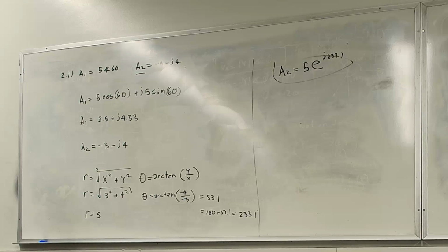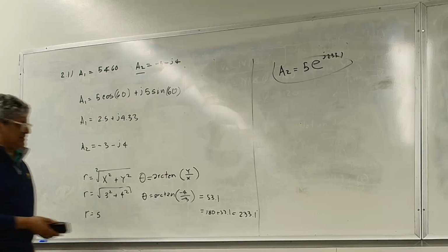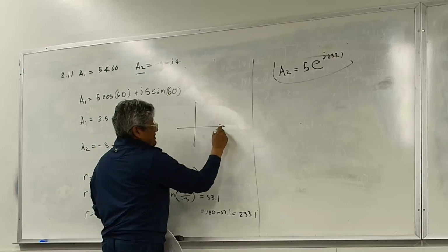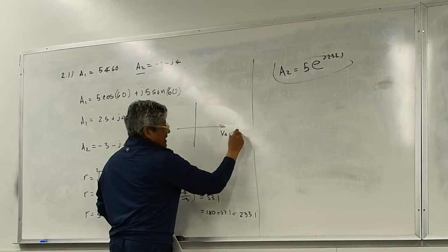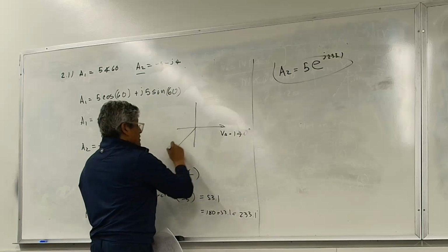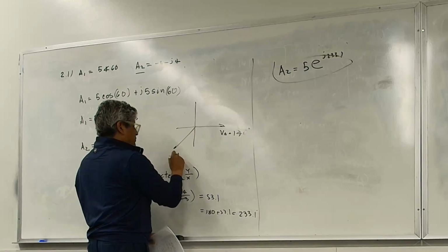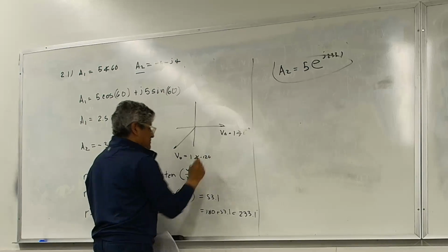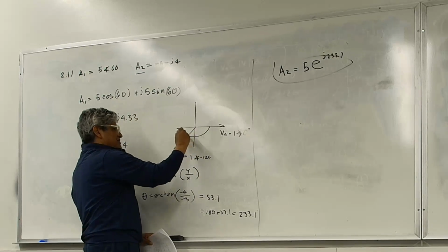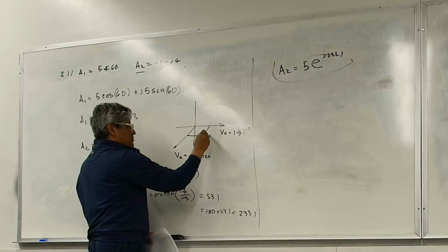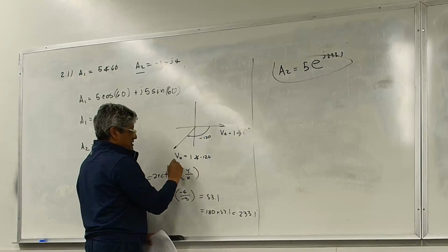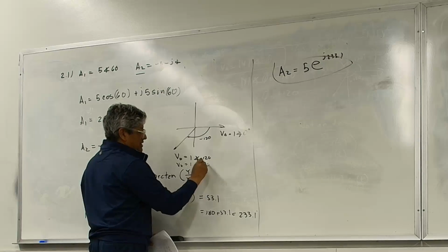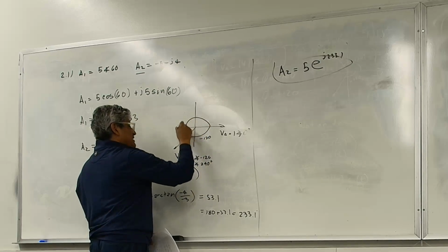Enter the values, with positive and negative angle, and you get the same thing. Remember when I talked about this too? I said VA is equal to, say, 1 angle 0, and VB is equal to 1 angle minus 120. That's because I'm measuring the angle in this direction, minus 120. But I can also say VB is equal to 1 angle 240, which is in this direction.